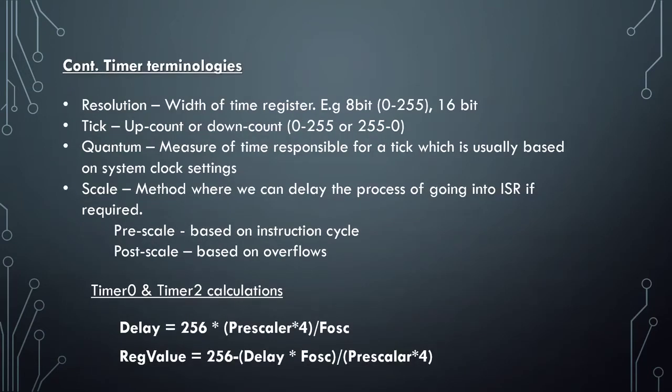So what are some of the terminologies used in timers? Just like we saw with the interrupt latency, in timers we have several terminologies that we really need to understand in order to use timers as counters in our programs. One of the terminologies is resolution. What is resolution? This refers to the width of the timer register, meaning 8-bit, 16-bit, and so forth.